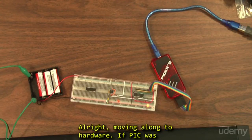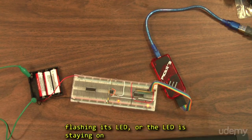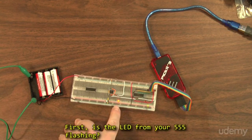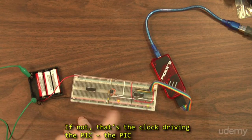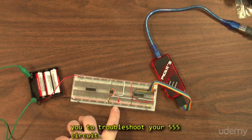All right, moving along to hardware. If the PIC was showing as programmed successfully, but it's not flashing its LED, or the LED is staying on permanently, there's some things we can check. First, is the LED from your 555 flashing? If not, that's the clock driving the PIC. The PIC will do nothing without a clock. I'll leave it to you to troubleshoot your 555 circuit.